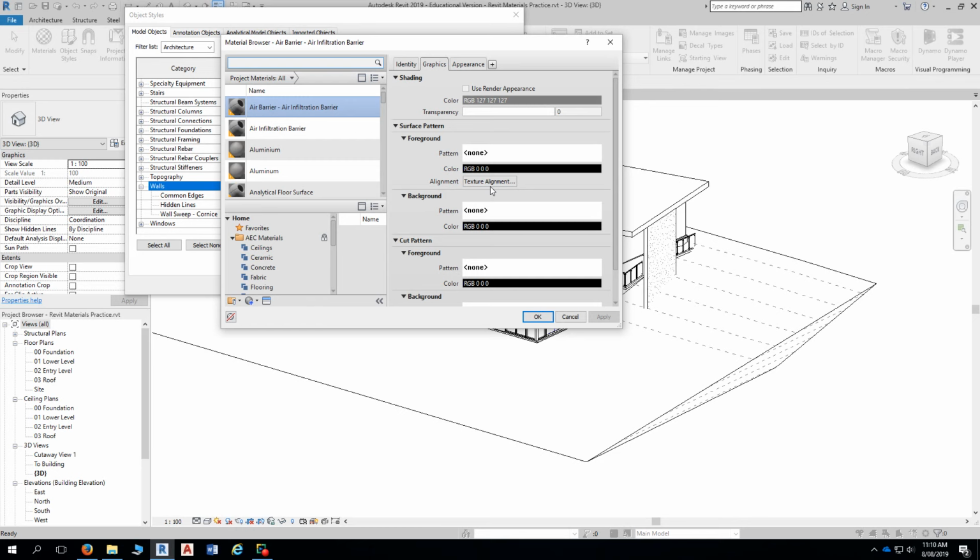Okay, because we're doing it at a category level, and really it's completely pointless to do that, because ultimately with walls, for instance, you're going to want different materials assigned to different wall types, aren't you? So there's no point in doing it really. You then have to go back to the wall type, so the wall type within the wall family. So we sort of go down to a type level, and the type level is by element. Okay, so type is element.